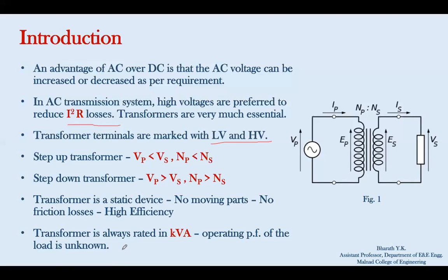Last point, transformer is always rated in kVA, kilovolt ampere. This is because the operating power factor of the load will always be unknown. That is why transformer is always rated in kVA.